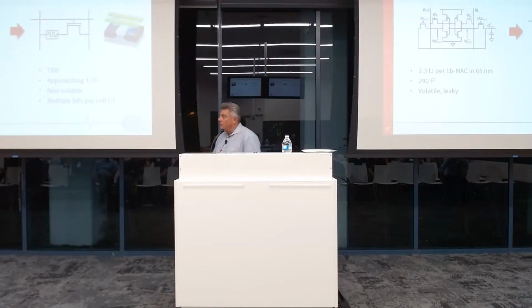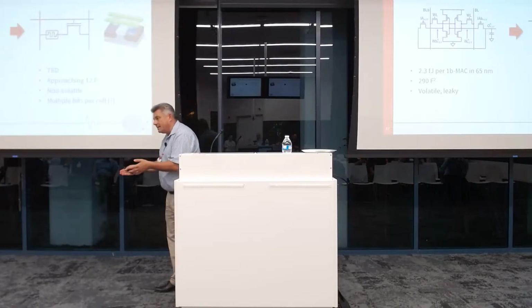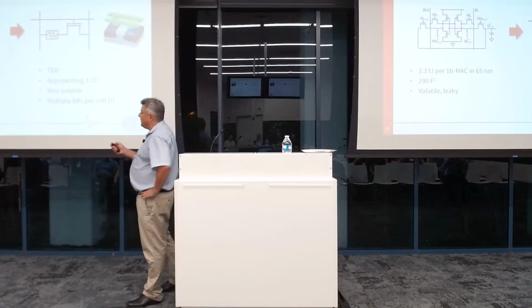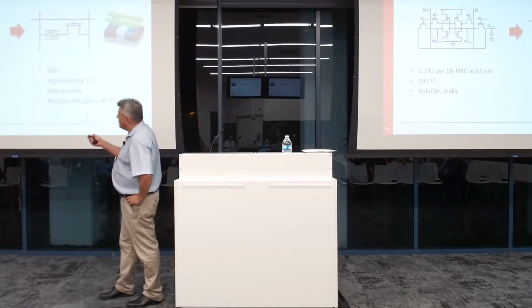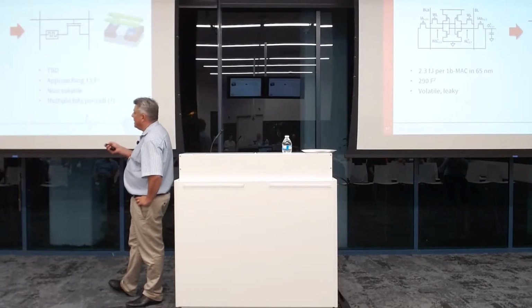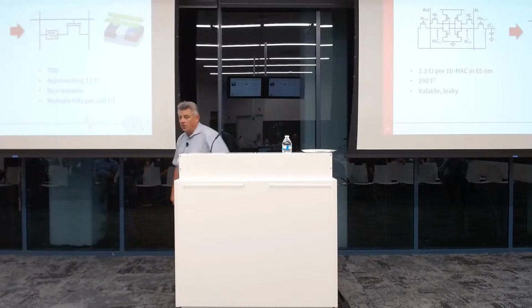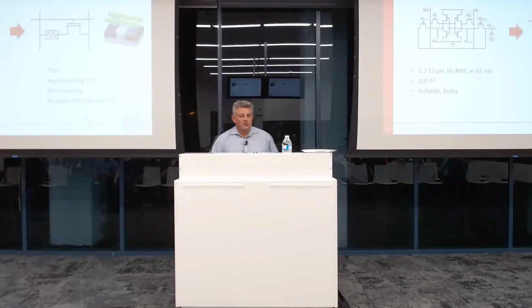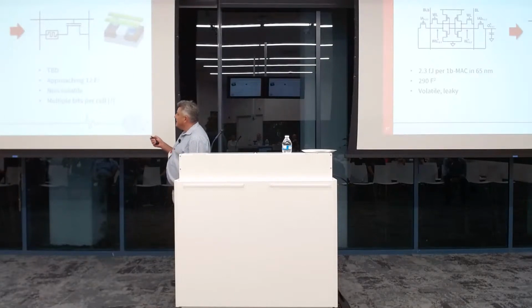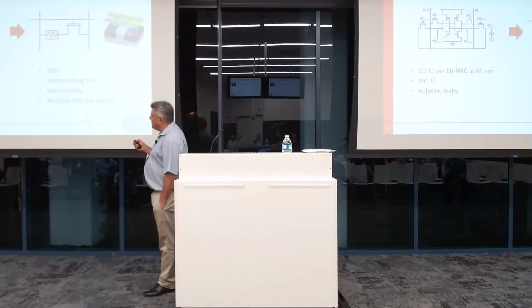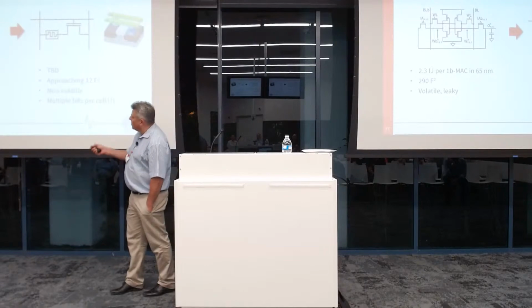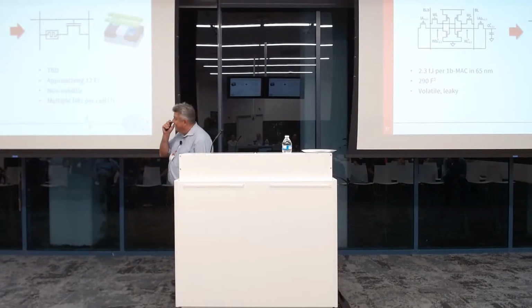But what's interesting for me now is to get the next level of density, which will also lead to the next level of efficiency. So a compute in memory SRAM cell, it turns out, is actually still very, very bulky when you compare it to an emerging memory cell such as RRAM. There's others like phase change memory and so on. You can pick your favorite one. But these are, if I trust the technology guys, approaching 12F squared. So these cells will be almost as dense as DRAM at some point. So it's sort of an order of magnitude smaller, more density than SRAM.